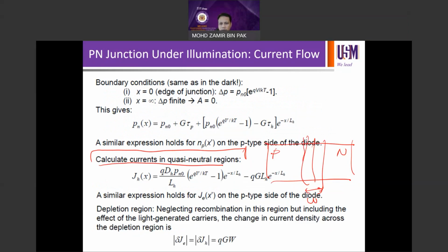Remember last time we learned that only this region has space charge, right? It's called the space charge region. But all the regions outside the SCR, outside the depletion region, are called the QNR, quasi-neutral region, which retains the polarity or the condition of the original PN semiconductor materials as you go away from the junction, right?